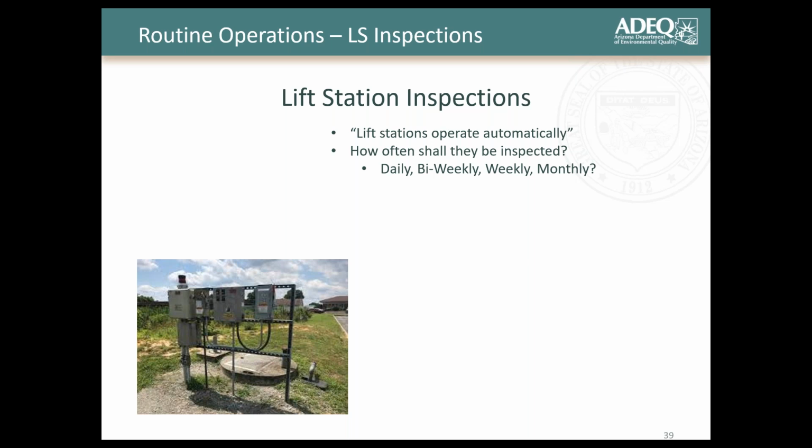In the system I used to operate, there were 13 different lift stations in our agency, and I can tell you there were 2 that we did daily. There were a handful that we did bi-weekly. There were a few that we did weekly, and there were maybe 1 or 2 that were offline that we would still check monthly for potential issues, even though they aren't running, obviously vandalism and things like that.